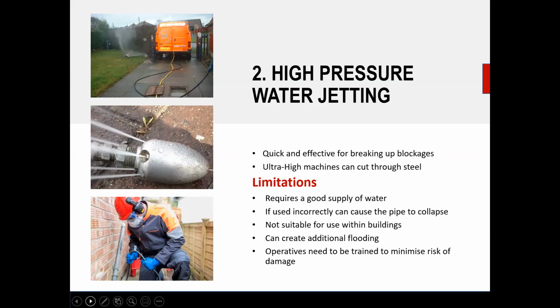So you have two options. One is to have a licensed standpipe and fill the water tank up at a licensed location, or connect into and take water from the customer's tap, normally an outside tap. If used incorrectly, this type of cleaning can actually cause the pipe to collapse. There's a WRC jetting code of practice for people to work to. If you're not too sure what the condition of the pipe is, and you're there on an emergency job, you keep the pressure low, below 2000 psi.